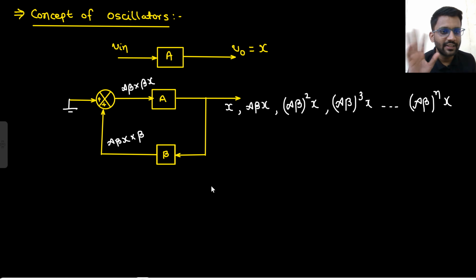Well, actually the loop gain is minus A beta, because what is the concept of loop gain? We studied it in feedback amplifiers: minus Vf by V test. So always put the negative sign. But forget about the loop gain; here what you understand is that in this loop you get a gain of A beta. Then again you get output that is being fed back to the input. Again you are getting A beta, A beta, A beta. So like that, this is your output.